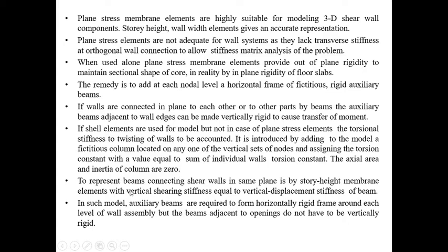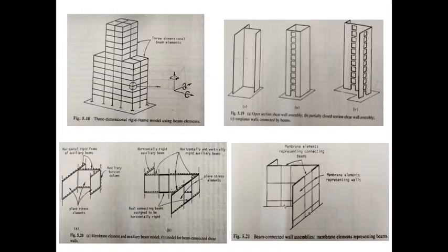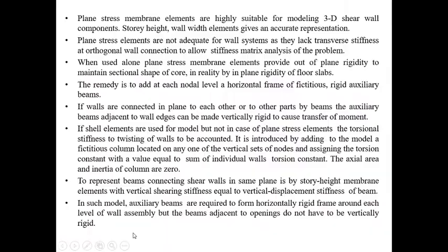Then, to represent the beams which connect these shear walls in the same plane, we use story height membrane elements with vertical shearing stiffness equal to the vertical displacement stiffness of the beam. Here the membrane elements are representing the walls, and here the membrane elements are connecting the beams. So this is the other type.